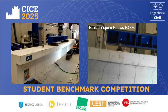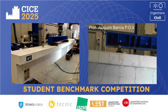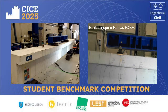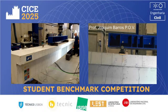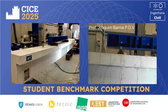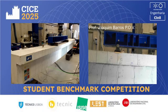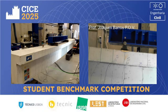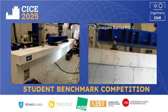Well, it seems that the difference between the two beams in terms of load capacity will be very small. It's hard for me to believe that it will exceed, because the crack width is quite significant in these two principal flexural cracks.